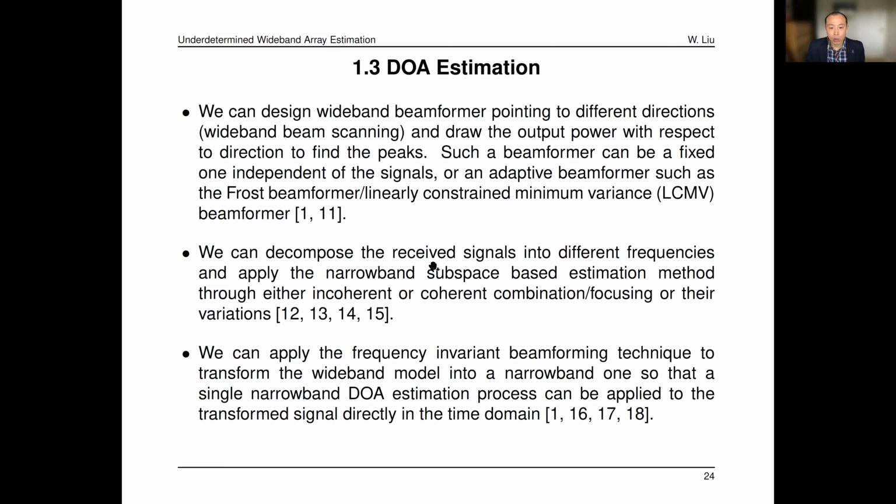Or we can decompose the received signals into different frequencies and apply the narrowband subspace-based estimation method through either incoherent or coherent combination or focusing, and all their variations. That's another set of solutions. And then we can also apply the so-called frequency invariant beamforming technique to transform the wideband model into a narrowband one.